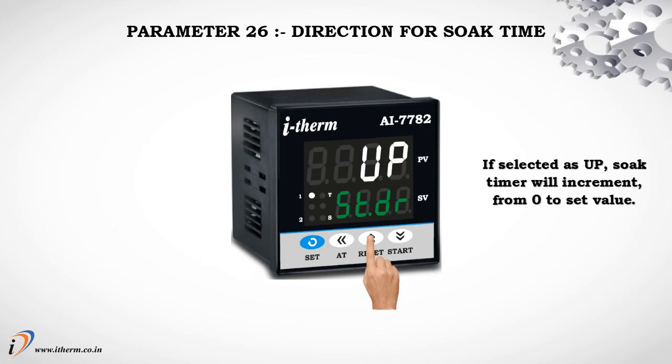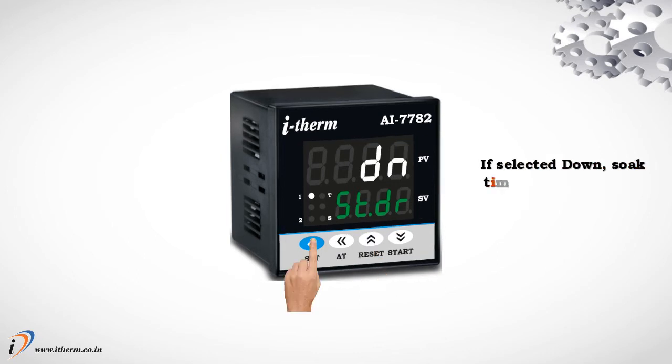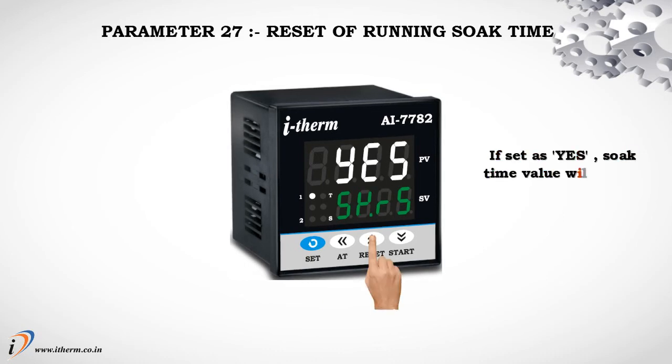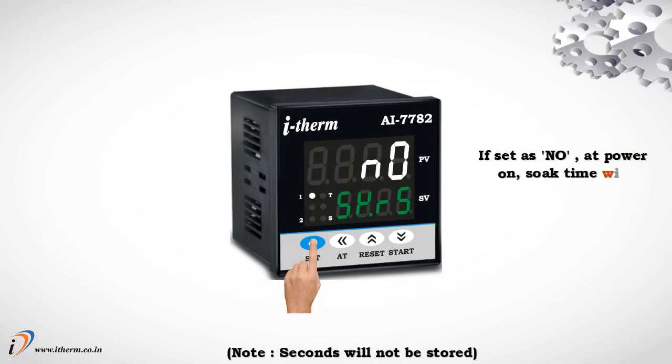Parameter 26, direction for soak time. If selected as up, soak timer will increment from 0 to set value. If selected down, soak timer will decrement from set value to 0. Parameter 27, reset of running soak time. If set as yes, soak time value will not be stored at the time of power failure. If set as no, at power on, soak time will continue from stored value.